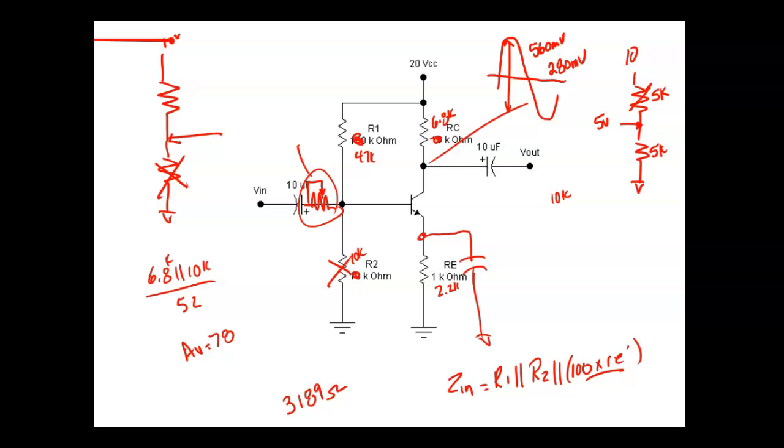It's a series circuit. I've opened a resistor in the series circuit. How much current flows through there? Zero. So V is equal to I times R, then V would be equal to 0 times 47K. What's that going to be? 0. So this guy drops 0 volts. I have 10 volts right there, this guy drops 0 volts, and we end up with 10 volts right there. Now that's not true, so I know it can't be 0.